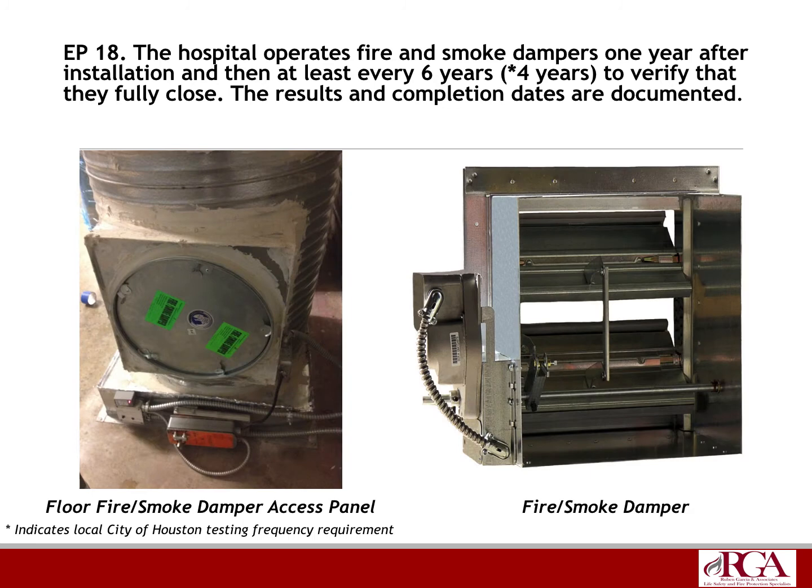EP18: the hospital operates fire and smoke dampers 1 year after installation and then at least every 6 years to verify that they fully close. In parentheses there, with an asterisk, you see 4 years. Here, the city of Houston requires us to test them every 4 years, regardless of building occupancy. The 6-year rule comes from being a healthcare or hospital occupancy. The city of Houston says, nope, we want you to do them every 4 years, which personally I agree with.